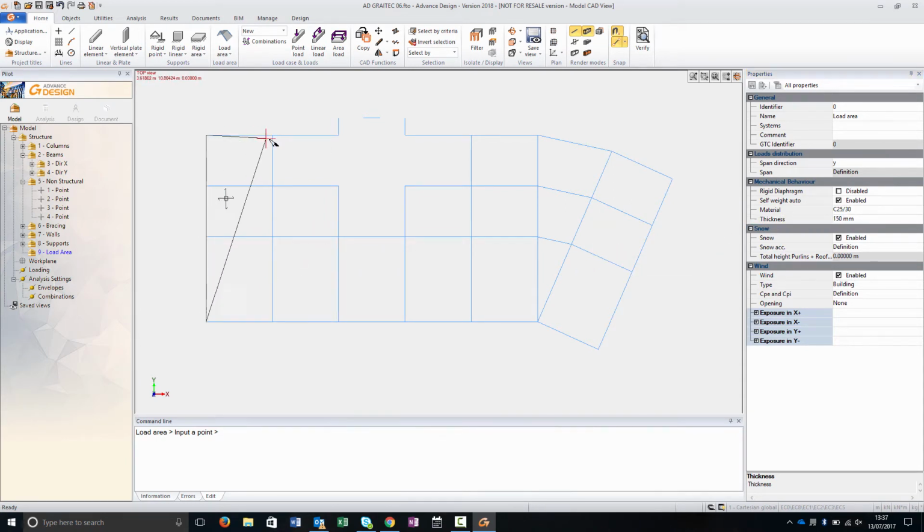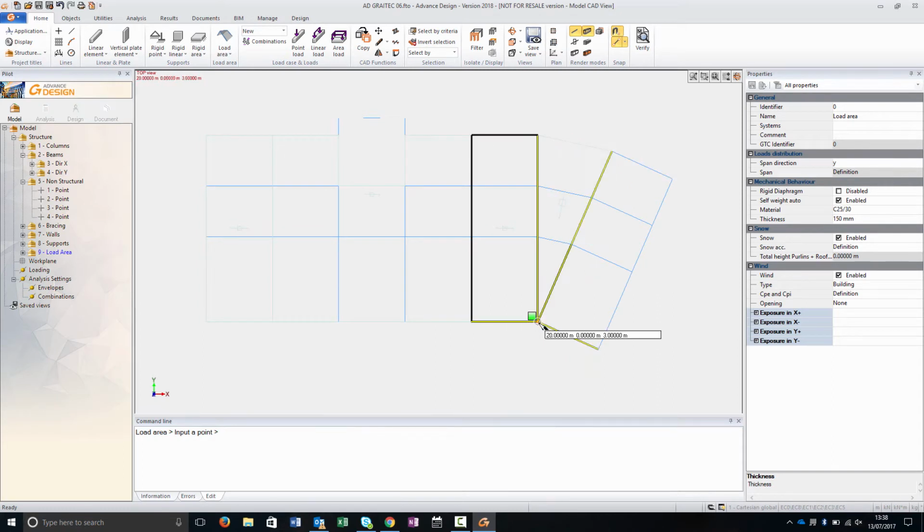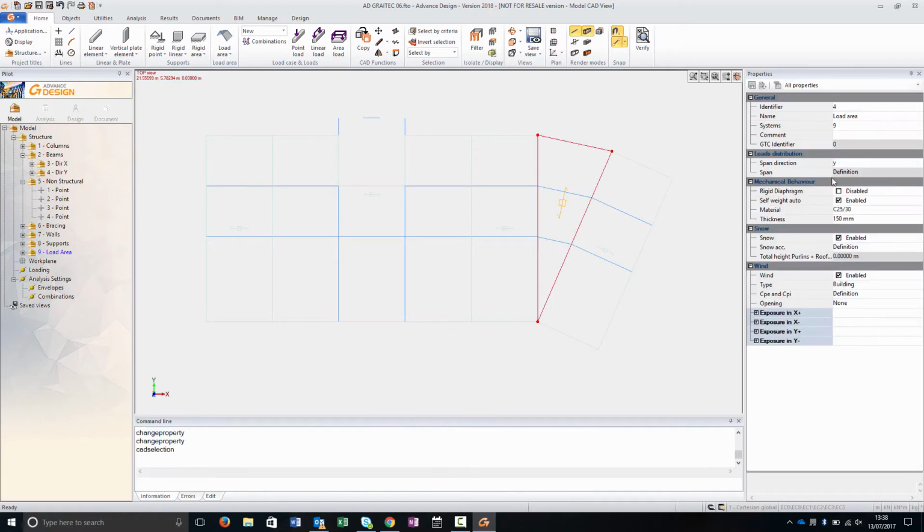We can create our raw materials and then set the density and thickness. If you want to mesh the slab with the structure, we can as well create plate elements that will be meshed within the structure and will give the stiffness required.